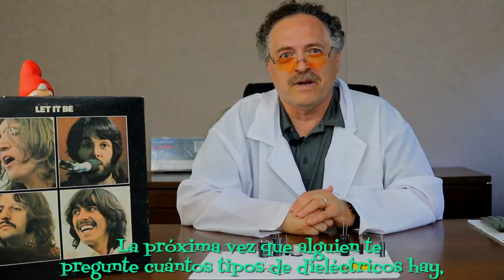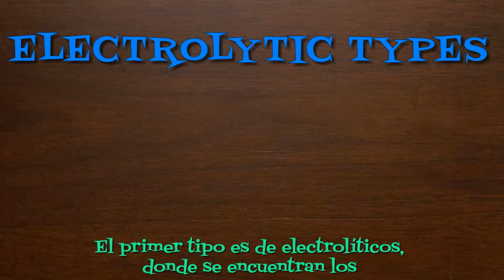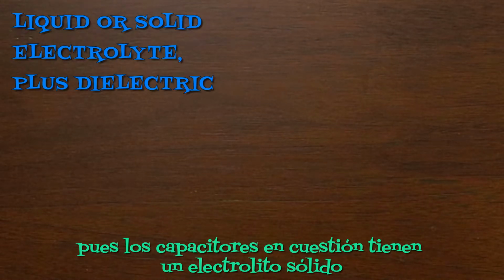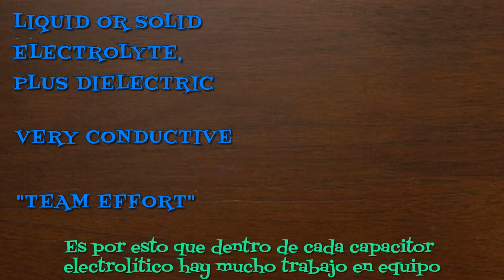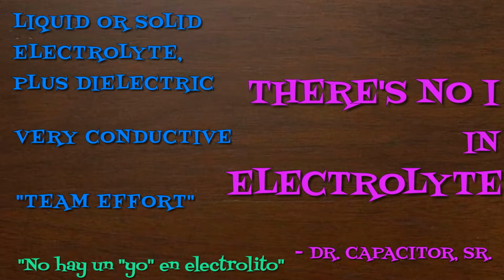Gladly. Next time someone asks you how many types of dielectrics there are, hold up the peace sign. 2 groups. The first is electrolytic types, home of your aluminum electrolytics, your tantalums, and aluminum polymers. They're called electrolytics because the capacitors in question have a liquid or solid electrolyte in them along with the dielectric. Electrolytes are very conductive compared to dielectrics. This is why it's a team effort inside each electrolytic cap. As my pop always said, there's no I in electrolyte.